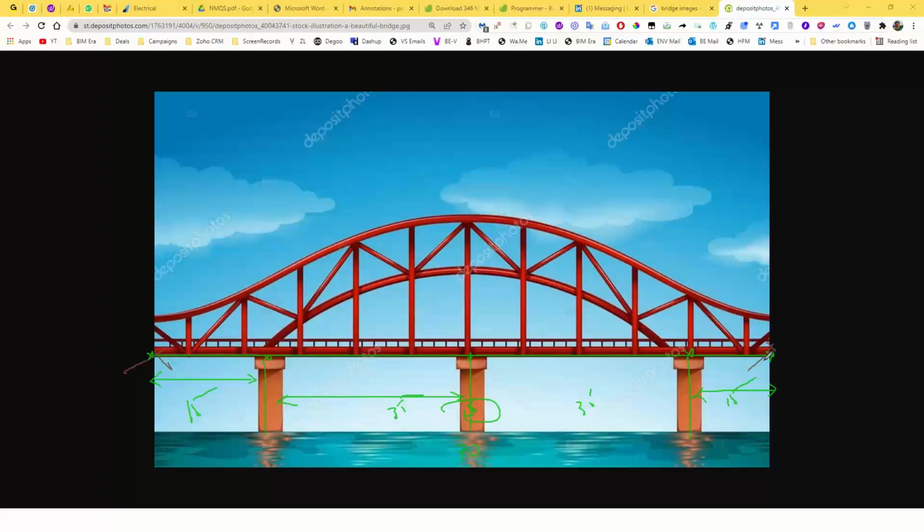We have a node to remove the first point and the second point. Okay, we have a node, or else if you don't have it, you have to create it. Like drop the first item, drop the last item. So I have 5 points. I drop the first item and the last item, so I have three points left. Those 3 points I'll be using to place my columns.